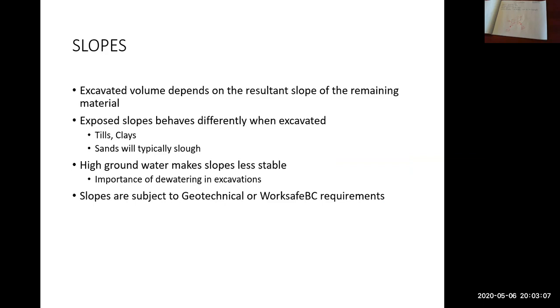You can imagine if we did not use that one-to-one slope, if we used vertical trenches, how much that vertical trench would reduce the amount of excavation that you have to do. So it's a significant amount. If you can excavate vertically safely, then you don't have to excavate nearly as much, which is cheaper.